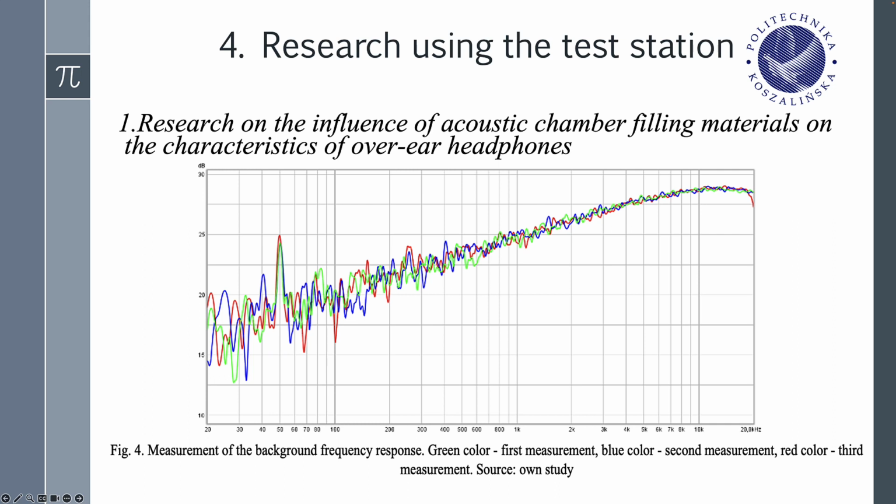The measurement was made in the human audible frequency range of 20 Hz to 20 kHz, and the time of a single frequency response measurement was set to the maximum length provided in the software, that is, 23.8 seconds, for the most accurate readings possible. In the case of the impulse response measurement, a white noise pulse of a very short duration was sent.